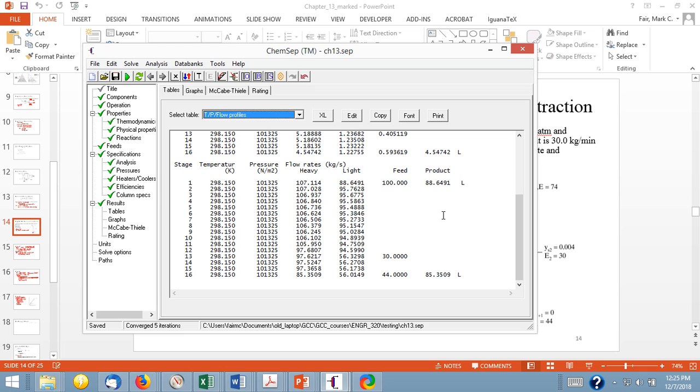So it's reached equilibrium with the other stream, which is water plus some butanol. But because there wasn't any water to begin with in the butanol stream, the net mass transfer is going into that butanol stream. Right? So if you look at what's happened, the heavy stream has suddenly decreased by that same amount. Right? It's dropped by something on the order of 12 in this case. Yeah. I thought that the water and the butanol were immiscible.